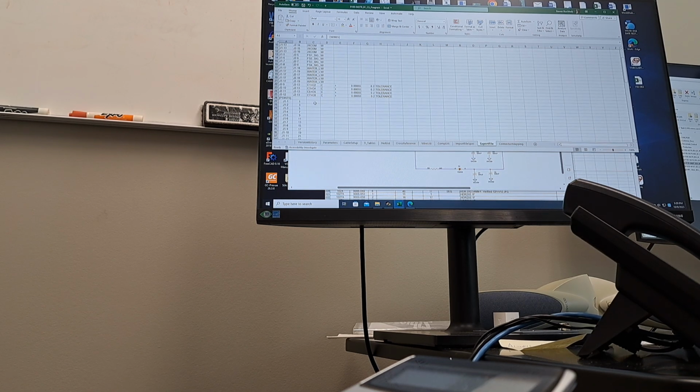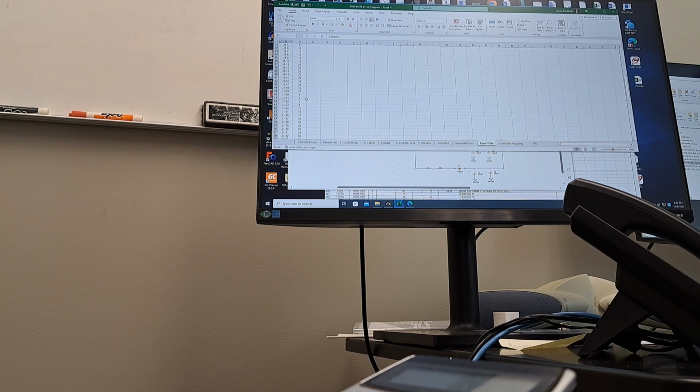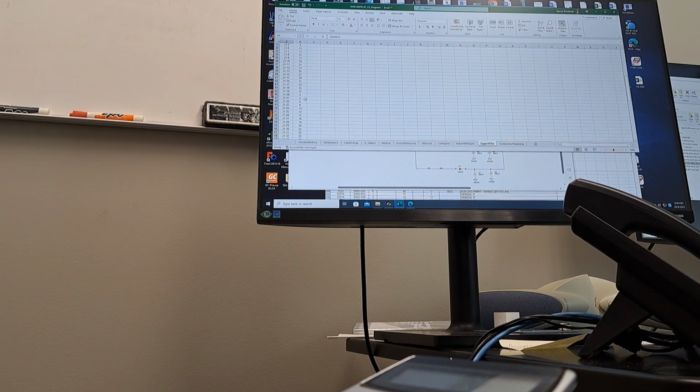And then here's all of the cross-reference information. So cable scan is going to say, oh, wire number 2 is really called J1 pin 20. So this is telling the cable scan what the names of each of the inputs are for the system. So it's all right there.